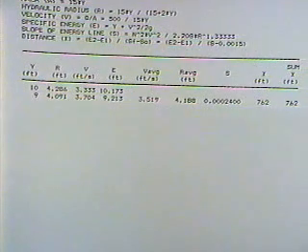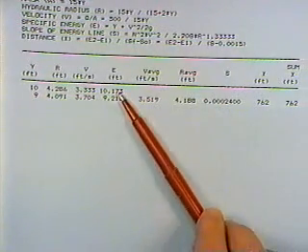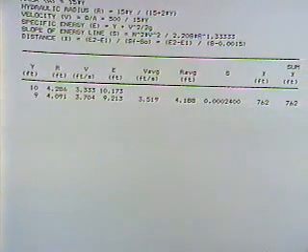We've got Manning's equation written in terms of S. We solve for S. And so we know the S, we know the specific energy upstream and downstream. We plug into our energy equation to get the X, the distance between those two sections. And then I keep a column to accumulate the X. Having done it, we can do it all over again.